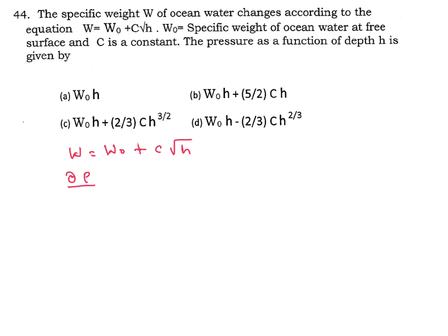This is Pascal law. Here del P equal to rho g del H. If we integrate this one, and rho g is specific weight, so del P equal to W del H, then we will integrate this one.